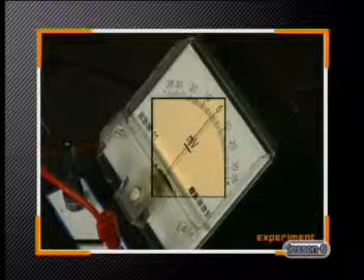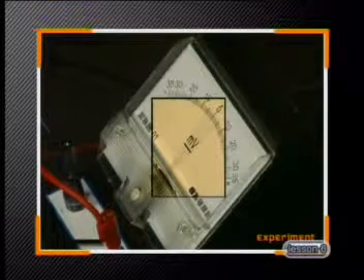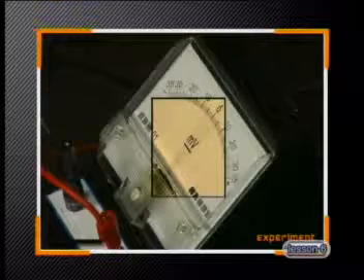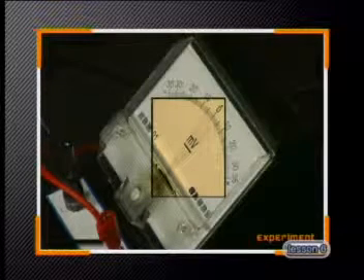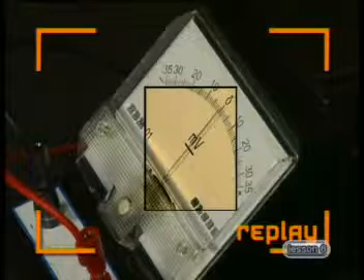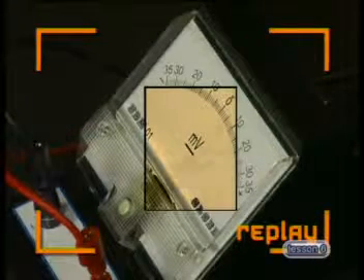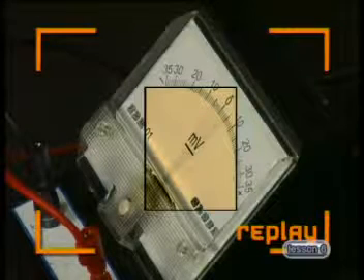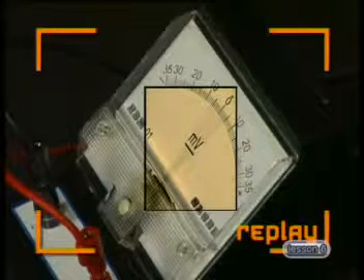Look, the needle of the galvanometer connected to the secondary coil vibrates rapidly, indicating that a changing potential difference has been induced in the secondary coil. Notice that the induced EMF is not constant, and so the induced current in the secondary coil will be an alternating current too. Now let's apply Faraday's law to each of the coils of the transformers in turn to derive a relationship between the EMF and the number of turns or windings on each coil.